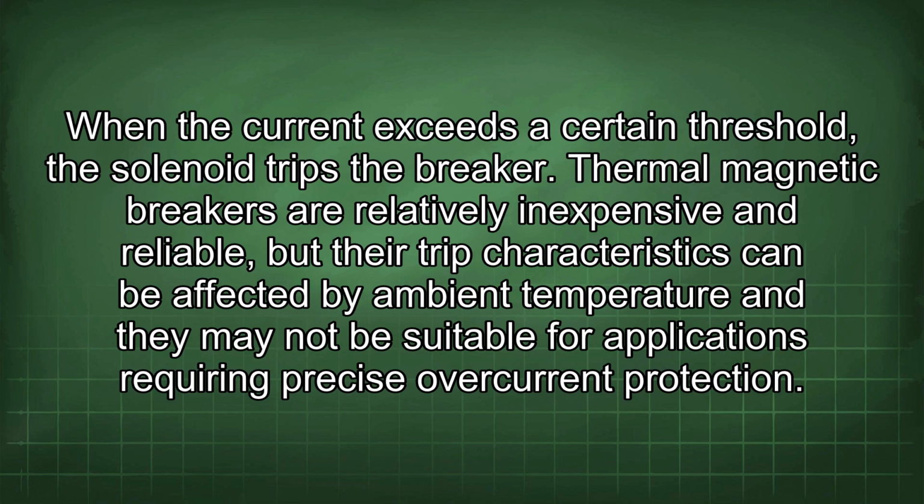When the current exceeds a certain threshold, the solenoid trips the breaker. Thermomagnetic breakers are relatively inexpensive and reliable, but their trip characteristics can be affected by ambient temperature and they may not be suitable for applications requiring precise overcurrent protection.